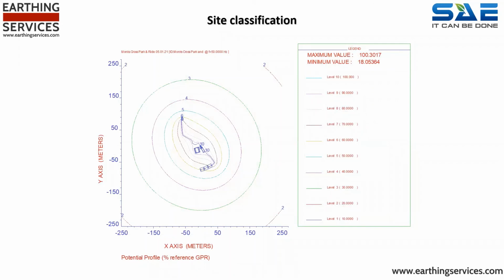If you think of the radiating electrical energy within the Earth during a fault current event, you must consider the consequence of what it might interact with. Should the discharging current encounter a more conductive medium, it is likely to discharge through that instead of the ground, as it will provide a path of lower electrical resistance. This can have significant consequences if the item through which the fault current is now flowing is a sensitive system.